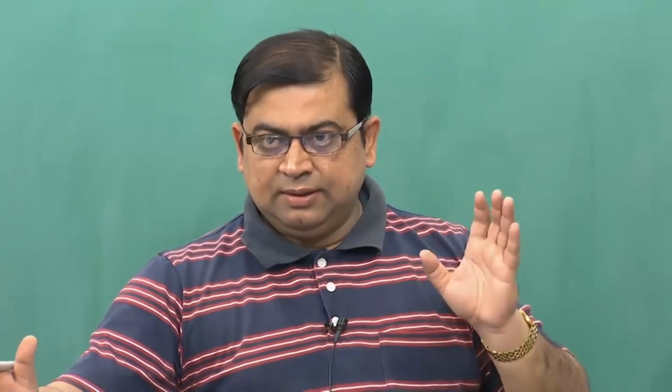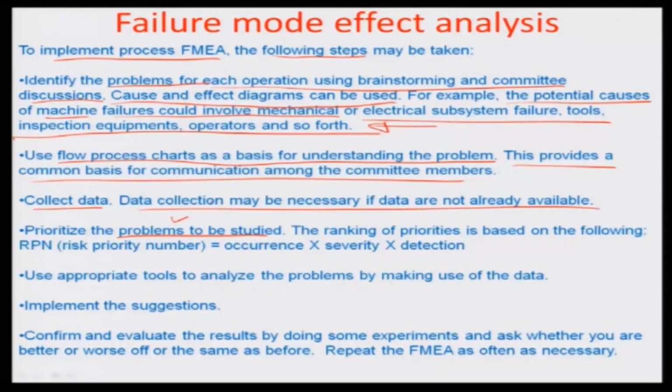First of all, let's focus more on the FMEA as of now, but there are organized methods in which this process data will come out, which will identify these are the problems, these are the potential failure modes associated with the particular stage of the process or the system that we are concerned with, okay. So then you prioritize the problems. Once you have identified the problems, you prioritize them, and the priorities are based on rankings, and these rankings are again done by those personnel who are involved in the process level itself, okay.